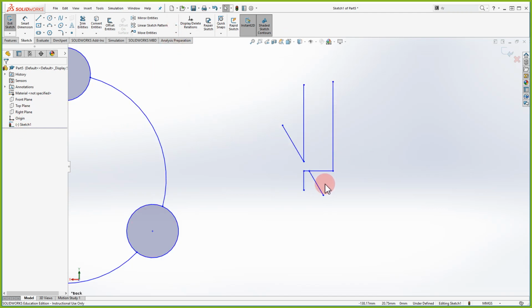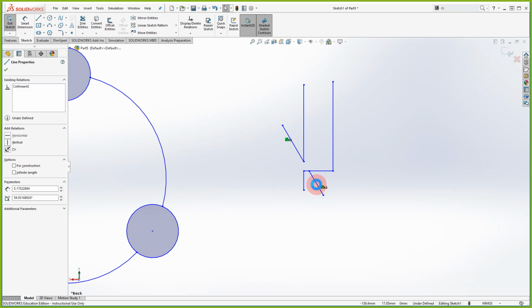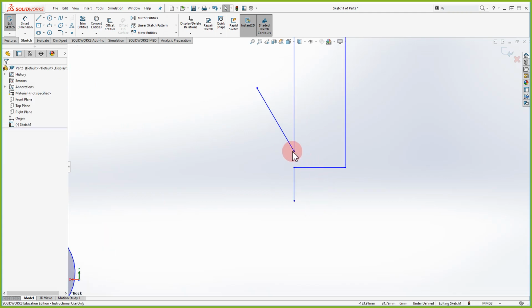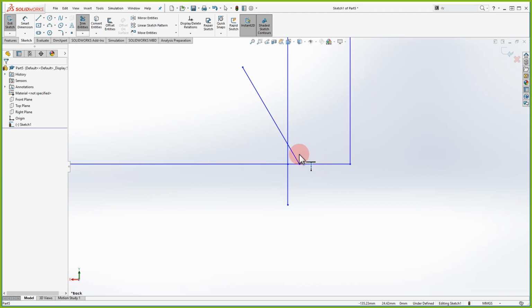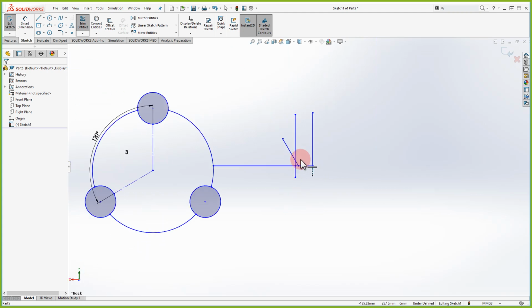For the extend option, which now that we have this drawing like this, if I want to extend this line to here, from trim, I go to extend, just click the object where I want it to go. Not clicking, just hover over, to be honest with you. And it's going to click the drawing where you want to go. So it's connecting to each other. So that was the trim, the extend, the pattern, the offset, the dynamic mirror, and the normal mirror.